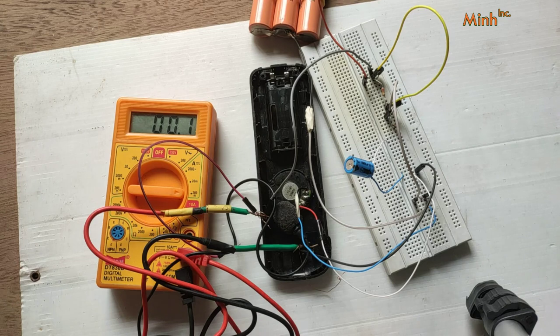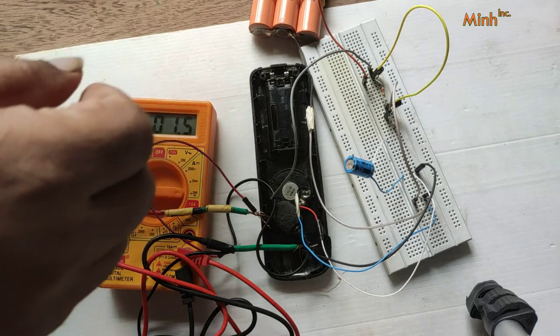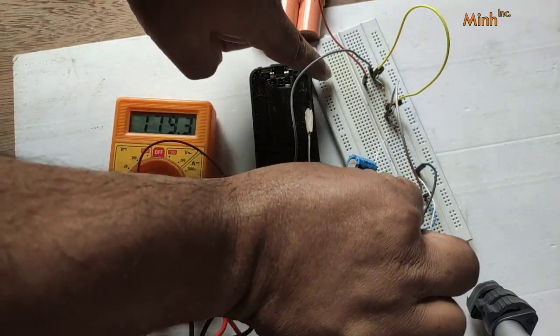So this is IE of the NPN and IC. Both we saw. 127 it goes, and around 102 milliampere the transistor goes cut off. So from 127 to 103, I think in that period the capacitor is discharging, and beyond a limit it is switched off. Next we will measure IB, then we will measure current in the capacitor.